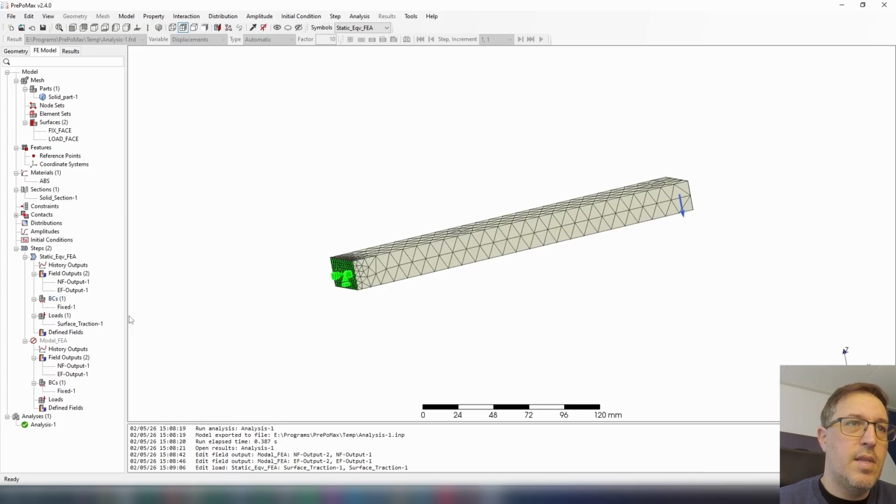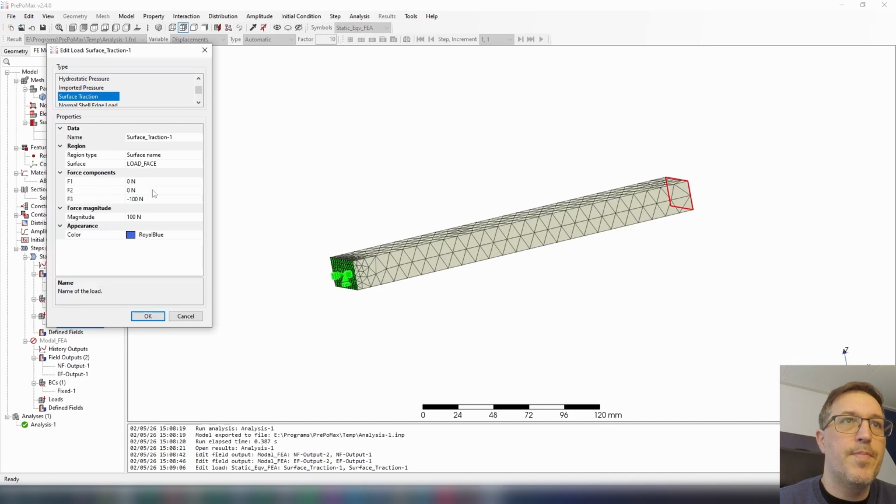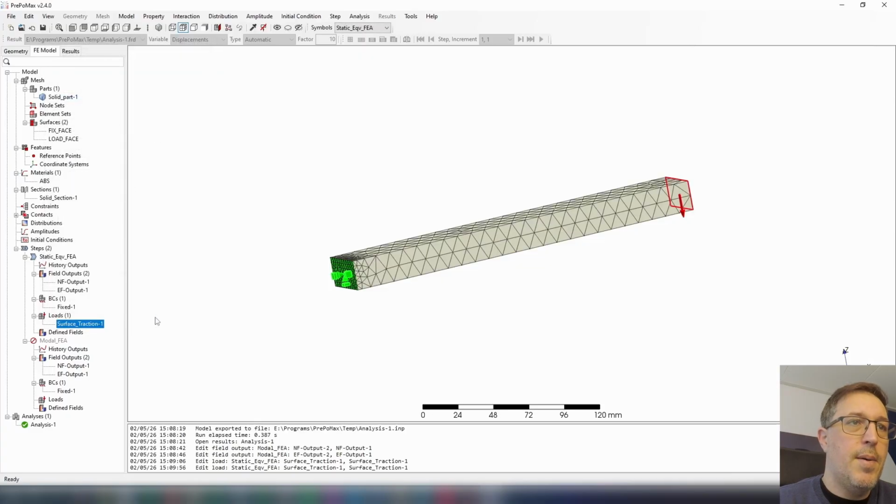And I found out that instead of having the load phases set up correctly, I had fixed phases instead of load phases. So the results didn't make sense to me, of course, because everything was 0. So I went back and I changed it, and now we're ready to go and continue with the analysis. Okay, so let's go ahead and run the analysis.